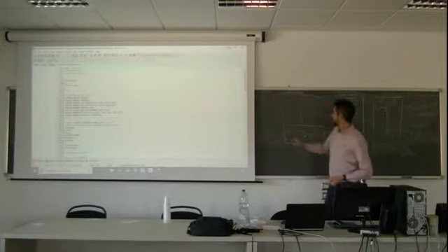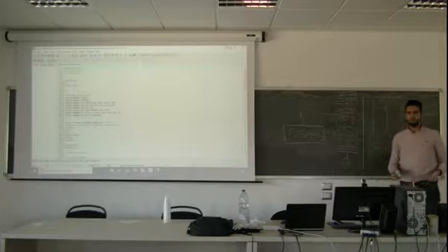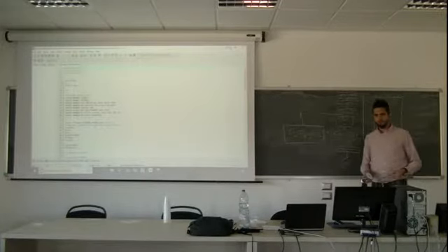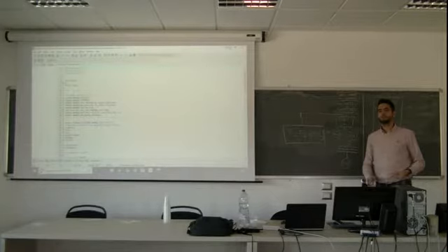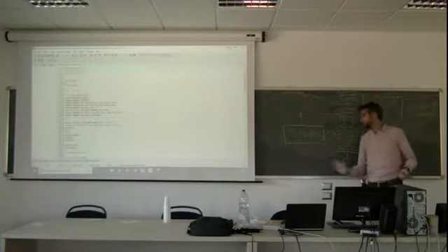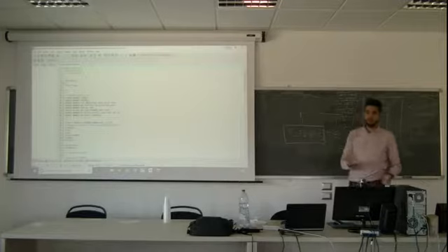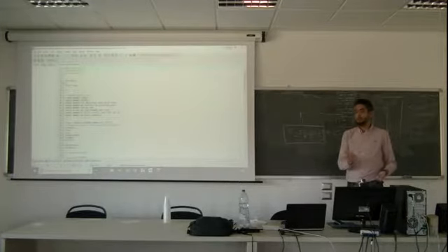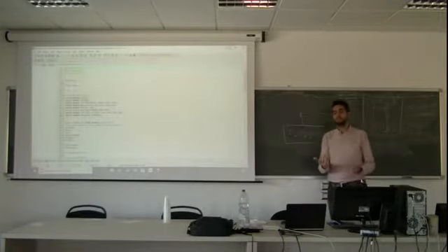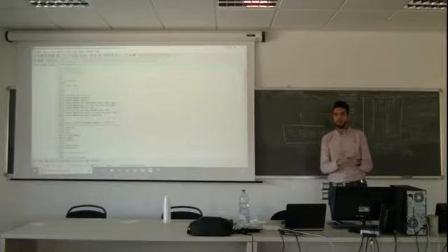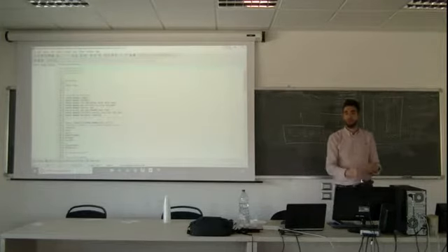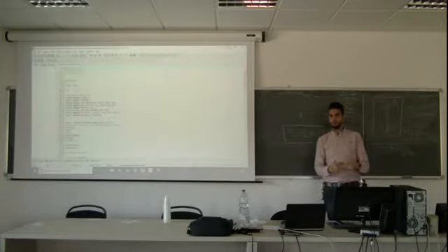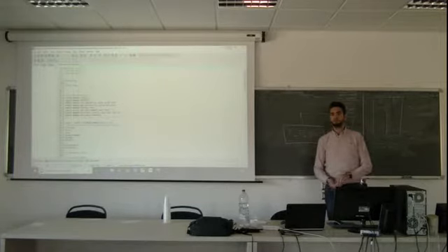Any question? When the number of iterations increases, does R stay constant or does it change? R usually is constant. You fix it. I recommend you put it as 0.9, for example. For a certain problem, you fix R and then let it calculate. If you see that you have convergence problems, try to relax your system more. It's a good tool. So that R is good for the entire problem.